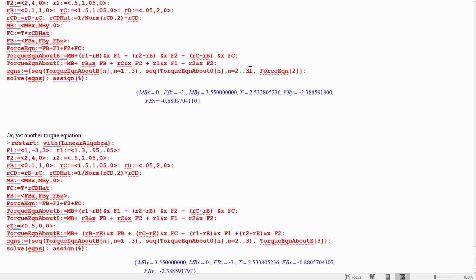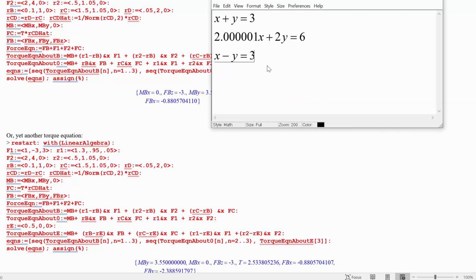So if you give it redundant equations, if you know that you should only have 6 linearly independent ones, but you're not sure where to take the torque, and you just put in 4 sets of torque equations, so 12 different equations, then likely you're going to end up with a different solution, or maybe even no solution, if it chooses to solve some of them first, compared to what you would have solved due to these round-off error things. So with round-off error in the mix, things that are really dependent on each other can appear like independent equations and end up giving you no solution, or at least a different solution if you don't have the full set of them than you're supposed to get.